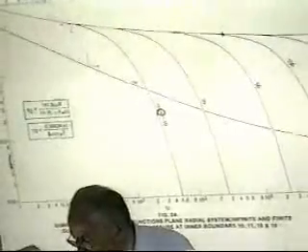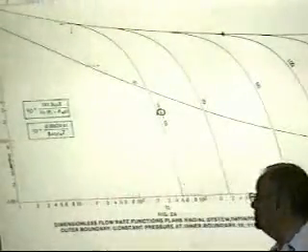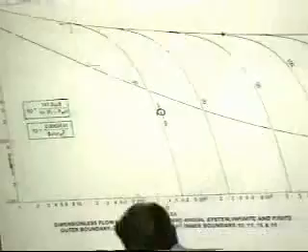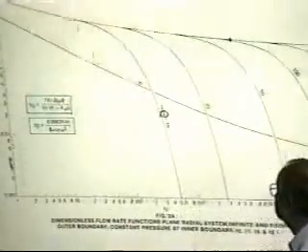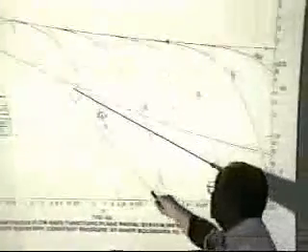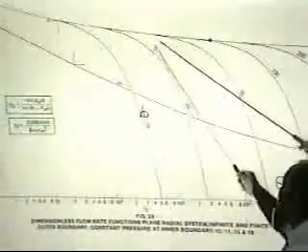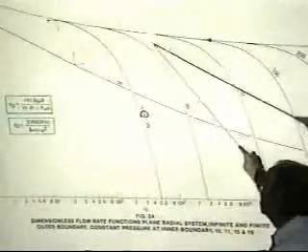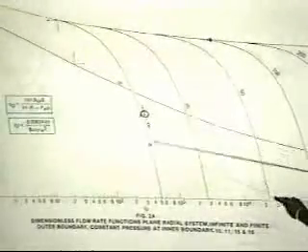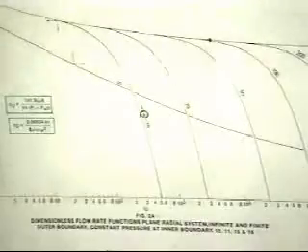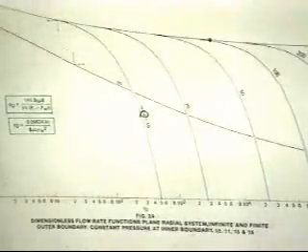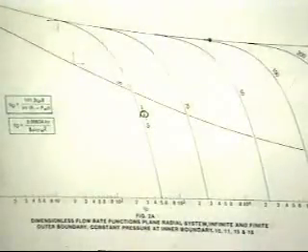I showed you earlier with the pD-tD. This is the qD-tD. I flipped it over. This is the infinite acting period down through here, and this is the depletion period. This period here is exponential decline. That's the single phase liquid solution, the analytic solution for constant wellbore pressure.